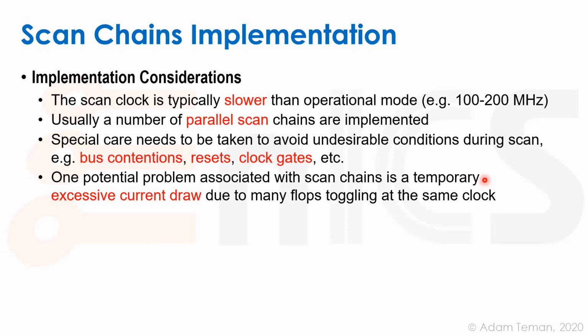Okay, one type of problem that I'm not sure exactly how it's dealt with: during scan, you're actually toggling the whole design. Usually the chip toggles a lot less of the design. It doesn't really toggle everything at once. That means there's a rush current that comes in on your tester. First of all, the chip might not work because you get this peak power draw.